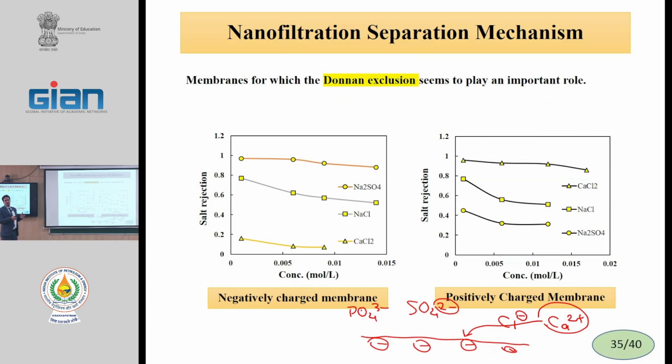Usually the wastewater pH is between 6 and 8, and when we say negative charge or positive charge, we mean in this range. For positively charged membranes, we usually use amine groups. With addition of amine groups, we can get positive charge. And for negative charge, we use hydroxyl, carboxylic, or carbonyl groups; OH groups can give a very low negative charge.